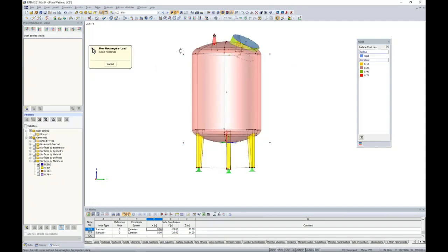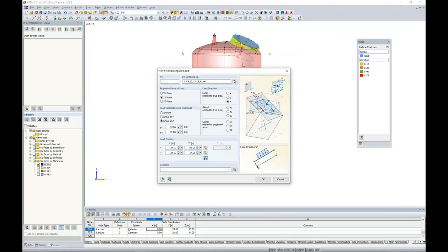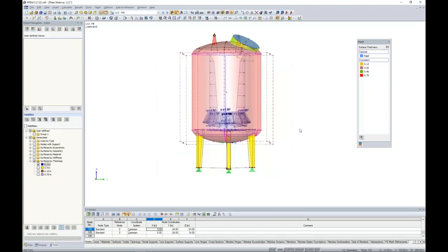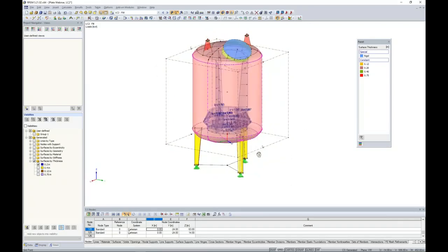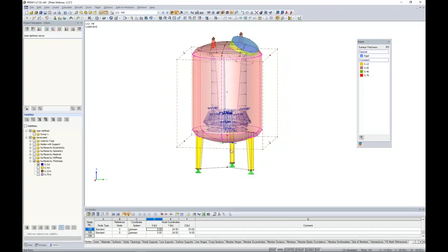So I cancel out of this visibility, and this was the whole purpose here of creating those strange exterior points. But now you can see when I click OK that I now will consider the fill load on the inside of this tank for all the surfaces that I selected. And even more so, it's going to vary linearly from 0 kips per square foot down to 0.4 kips per square foot. And in webinar 2, this will make a little bit more sense once we can actually look at the load distribution. So of course, for additional fill loads, maybe we'd want to account for friction in the vertical direction and have several more load cases.